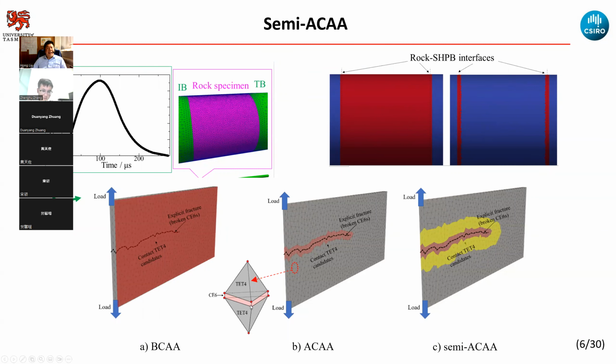For this cohesive element, before it fails, we deal with it using the cohesive bond force, or the repulsive force. After failure, the cohesive element is broken and we transfer to contact. Then we use contact mechanics to do the calculation.